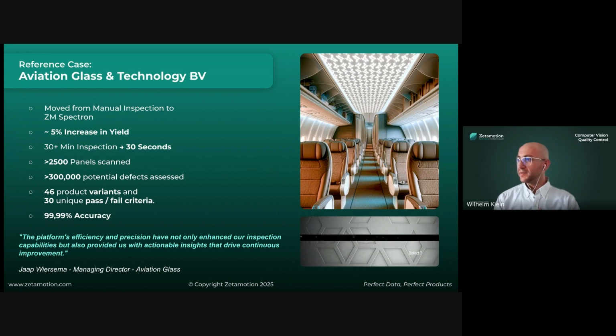Can the system only scan 2D flat panels, or can it inspect 3D products? The system doesn't really care. So mostly this is a hardware challenge or question. Of course, it's much easier and straightforward to do flat products, because you can mostly get away with area scan cameras and maybe something like a laser line scanner. And 3D objects can be a bit more difficult. You need a turntable, or you might need some kind of robotic solution to make sure you are capturing everything.